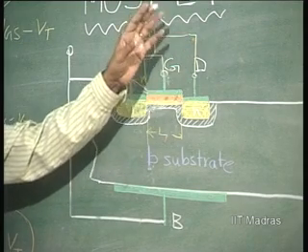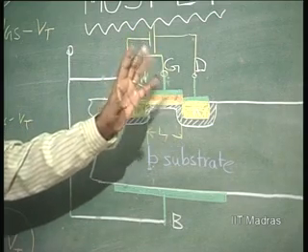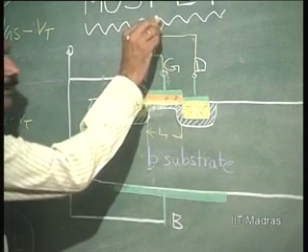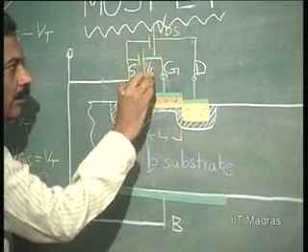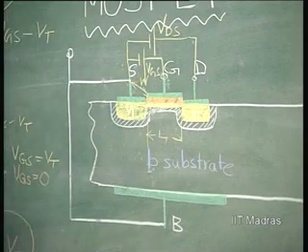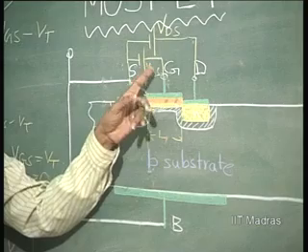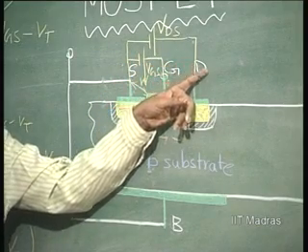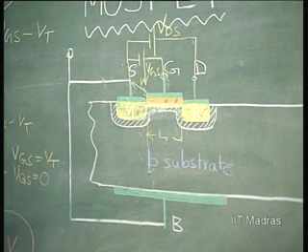It should decrease. At the drain end, it will start decreasing as I start increasing my value of VDS, because this VDS is opposing VGS in forming the net VDG, the channel width will decrease.